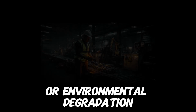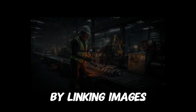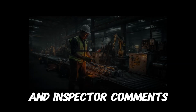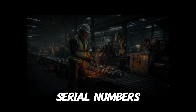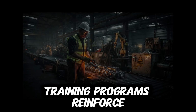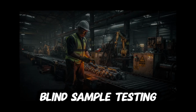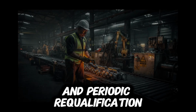Trend analysis of visual findings can reveal emerging issues such as tool wear, material batch variability, or environmental degradation before they escalate into field failures. Digital inspection systems enhance this integration by linking images, measurements, and inspector comments directly to component serial numbers and enterprise resource planning databases. Training programs reinforce procedure adherence through competency assessments, blind sample testing, and periodic requalification.